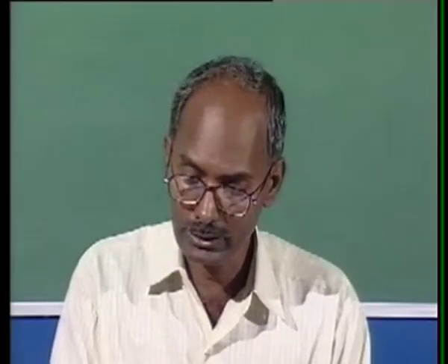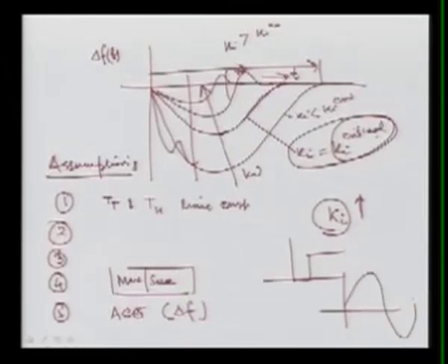So for measuring the frequency, at every point that we are measuring, we then calculate the frequency. So it was assumed to be continuous, but in reality the measurement of the frequency deviation, that is the change in delta f here, takes place in a discontinuous, sampled data fashion.